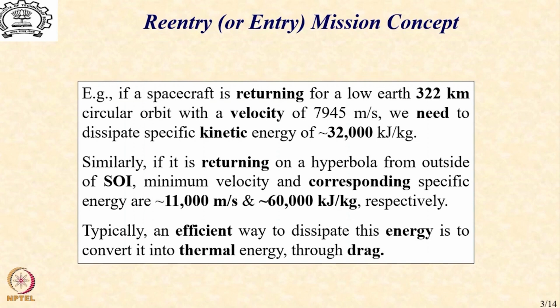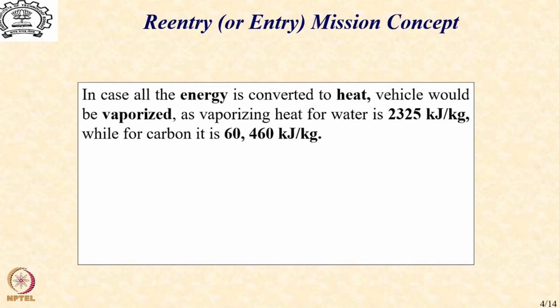So you allow the drag to retard the vehicle, and that energy which is consumed by the drag appears in the form of heating of the vehicle, and if you can manage the heating, then it is possible to dissipate the energy in an efficient manner. So supposing we were to do this to complete the return mission, what would happen?